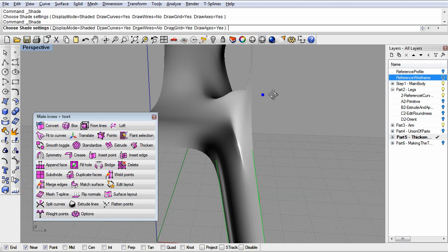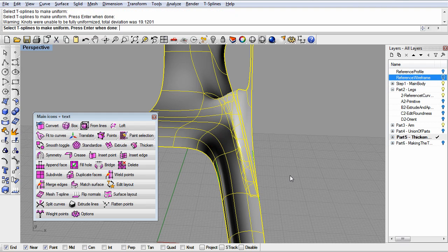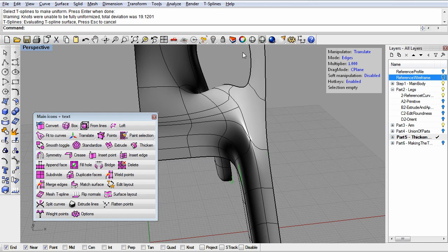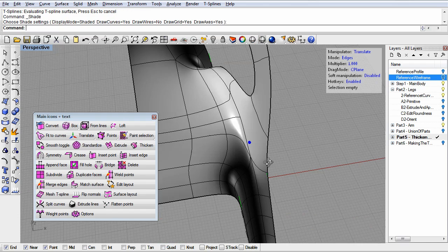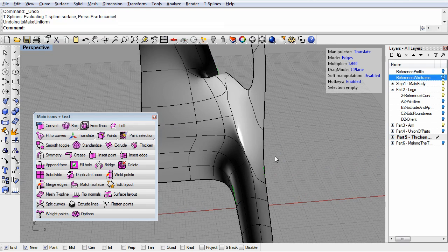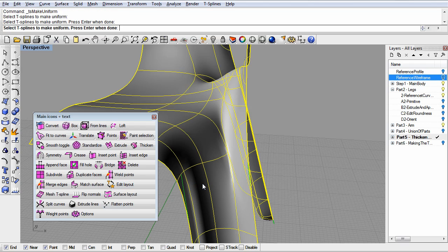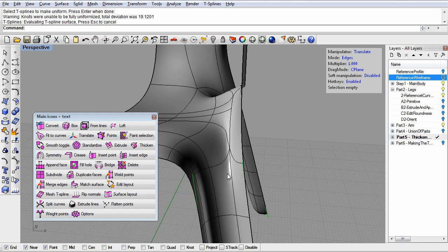in some places. And if we run the MakeUniform command by right-clicking on this button, hopefully that will look a little bit better. Let's see what it does. Okay. So you can see that really spaced things out quite a bit better. Let me undo and redo that so you can see kind of what happened. So here's before we'd made uniform. You can see things are kind of pinched. Now if we do the MakeUniform command, it will really space things out a lot better.